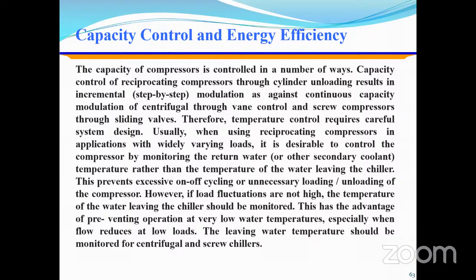Usually, when using reciprocating compressors in applications with widely varying loads, it is desirable to control the compressors by monitoring the return water or other secondary coolant temperature rather than the temperature of the water leaving the chillers. This prevents excessive on-off cycling or unnecessary loading and unloading of the compressors.